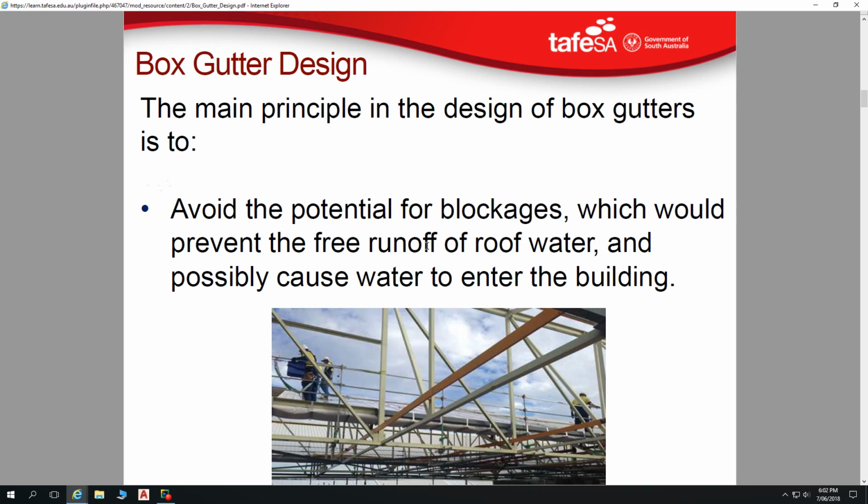But then your box gutter finishes there like that, and the water flows in via that sloping mesh top. So it's great for hay sheds because you get hay and all those blown around bits on the roof. You're getting plenty of debris in your box gutter, so that debris continuously gets left on the mesh top where it dries and goes away.